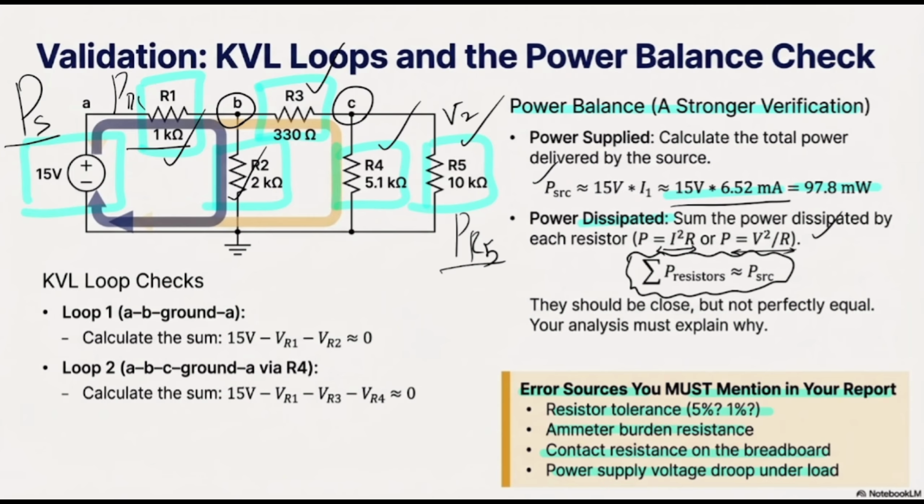It would be better to consider one source at a time, which means you have to get rid of one of the sources. If it was a voltage source and you want to get rid of it, your voltage V is going to be 0. V equal to 0 means that it is a short circuit, or is going to be considered as a wire. So instead of the voltage source, you consider a wire.